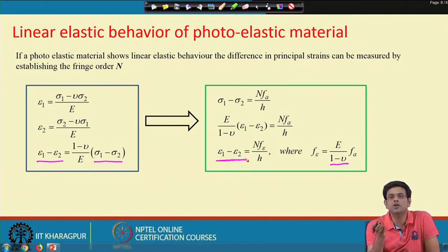With Cauchy's law, we can express the traction and the stress in terms of normals. Now, if we remove n1, n2, n3, the direction cosines in different directions, we get a relationship between the traction and the principal stresses. This relation represents the equation of an ellipsoid, known as the stress ellipsoid, which represents stress at a point.